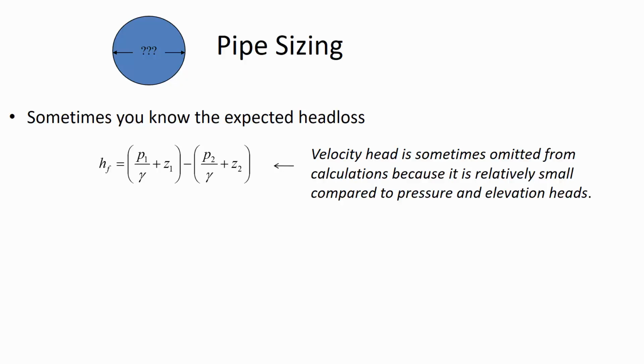This is relevant, but when you have a pipe that's underground, can you have pressure added to the depth underground? Pressure added to the depth? Yeah, like to the water from it being underground at a certain depth. Well, here there's more water pressure in the pipeline here than there is when you go back up above the surface. And also, if you had a hill, let's say that the hillside is sloping this way. You're gaining pressure because you're getting further and further away from there. But there's not like anything magical, just like the soil pressure on the pipe. That's not going to get any usable pressure that way.